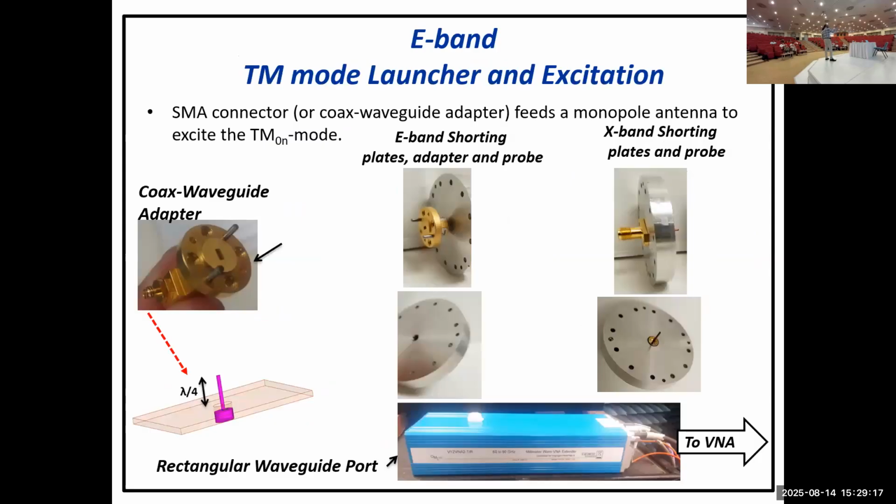Now this experiment is for an E-band BWO. E-band is around 78 gigahertz for this one. E-band is 60 to 90, right? This is a very high frequency, millimeter wave BWO, and we have designed a millimeter wave BWO. We have 3D printed it with copper plating, and we have tested it with high voltage. And also we have machined it to compare.